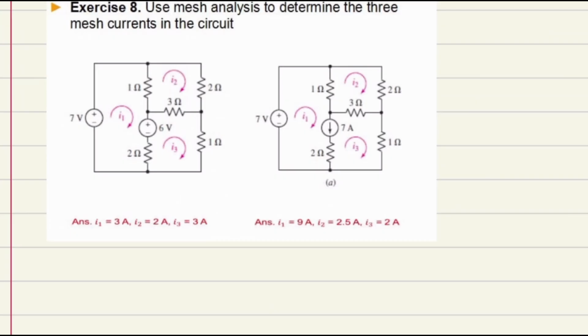So let's consider these two questions and see whether we can solve them. As you can see, instead of only 2 meshes, we have 3. So I have one mesh, a second one, and a third one. First of all, I have to specify all of the currents, for example, positive and negative over here. It doesn't matter which way you choose, because at the end of the day, if you use your equations, they are going to cancel out each other, right?